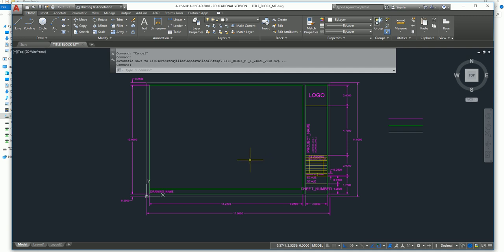There we go. So like I was saying, the title block usually houses information: project name, if you have an address, your sheet number, different things like that. Scale, if the whole drawing's per scale. Sometimes you'll put scale per drawing because, especially on detailed drawings, you may have like 4 drawings on one page. Each one's a little different scale.